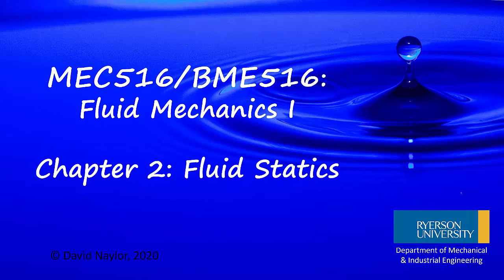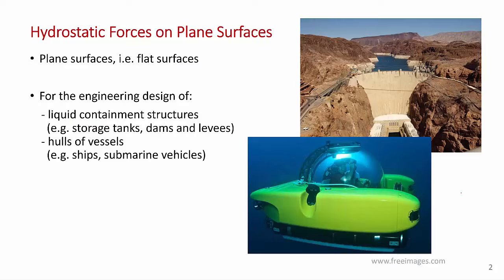Okay, continuing on with Chapter 2, Fluid Statics. The topic of this presentation is hydrostatic forces on plane surfaces, and this kind of analysis comes up in engineering design when you're looking at things called, I'm going to call it liquid containment structures, things like storage tanks, dams, levees. It's also important for determining the forces on the hulls of ships and things like submarines.